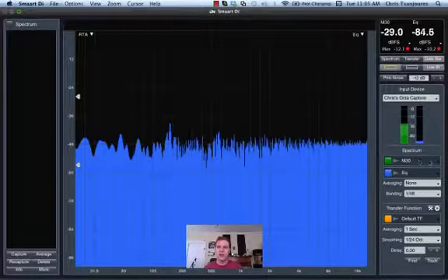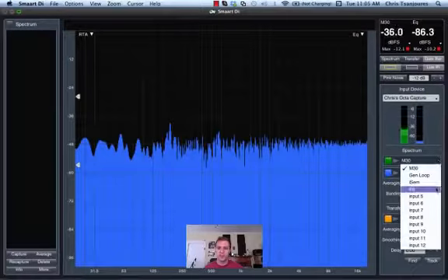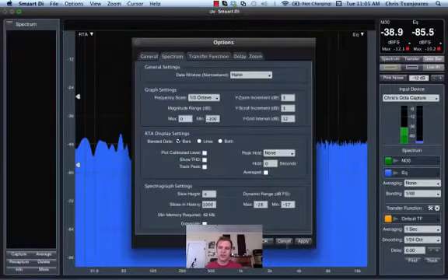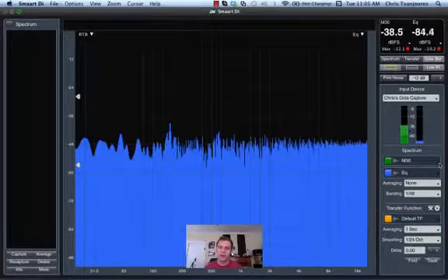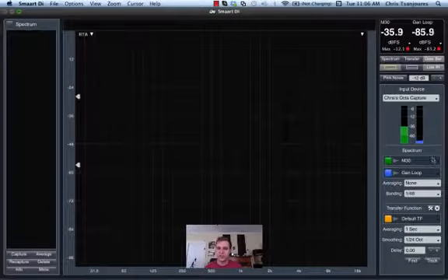Now I've got all these different channels set up, and I'm going to be switching back between them. But what I want to do is have many configured pairs for when I'm doing the transfer function measurements. This first pair that I'll be using will be the M30 against the generator, so I'm going to name that my M30 or mic 1 pair.